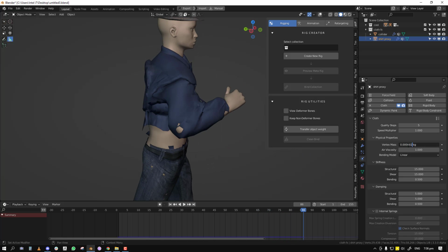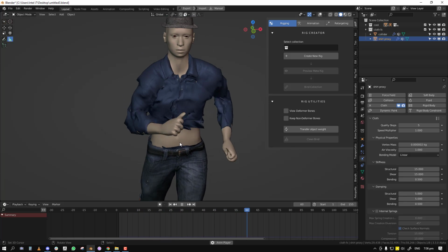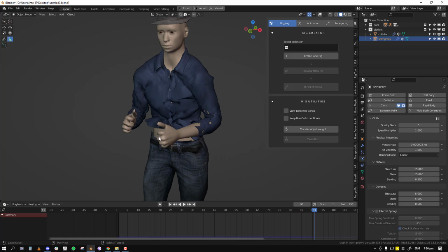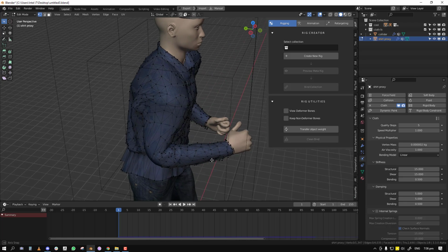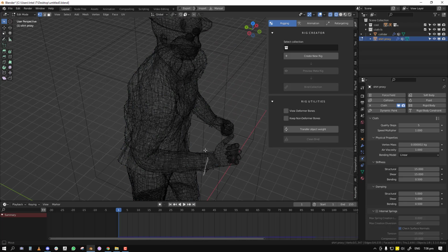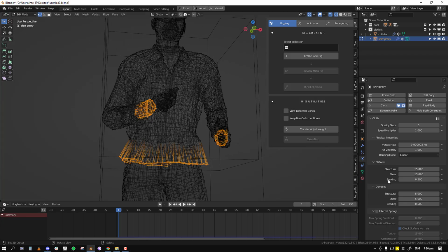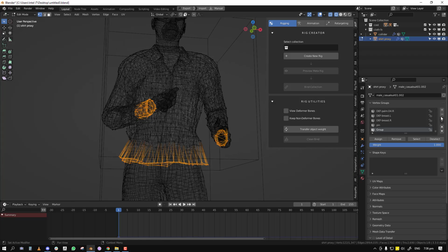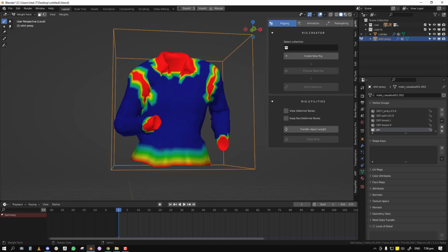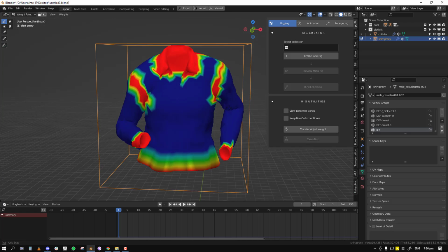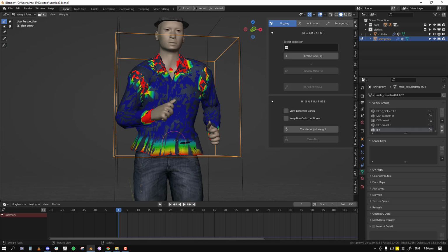Reduce this some more. So the size of your scene also matters in playing with this value. Okay, I think the solution which I showed you is not working, so we just need to pin the edges. We'll add it to the pin, so it will look like this. Basically, all the edges that have the face capped up, you want to make sure it's pinned.